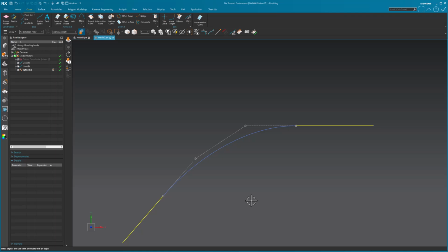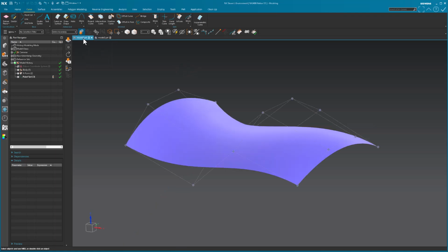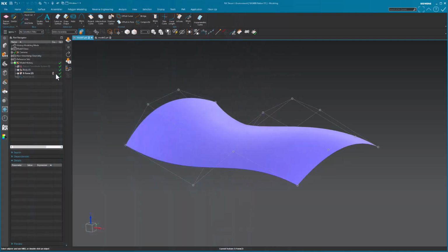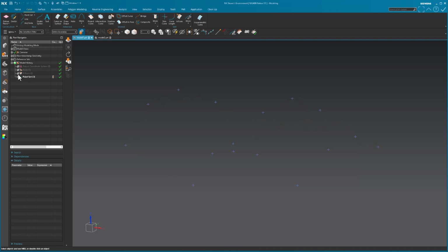And I've done a lot of things over the years. Now, the reason why I'm using NX to demonstrate this, very long-winded video, is I'm going to go over here. And what I've done is I've made a surface. I X-formed it, right? 3 degree by 3 degree, single patch, and I extracted the points. And I'm going to go ahead and hide that X-form. So those are the points that make that surface. Now, I should say control points that make that surface.